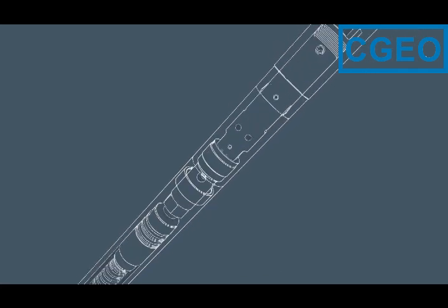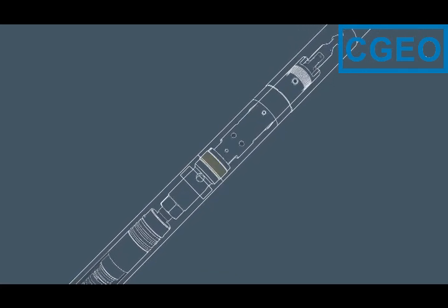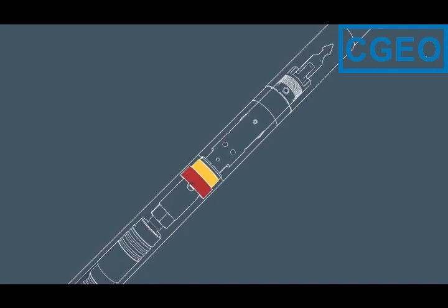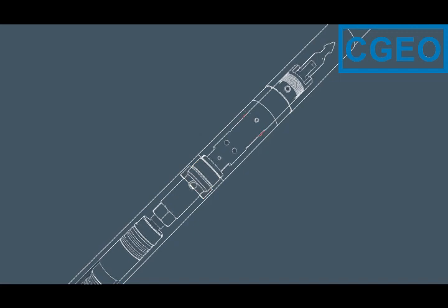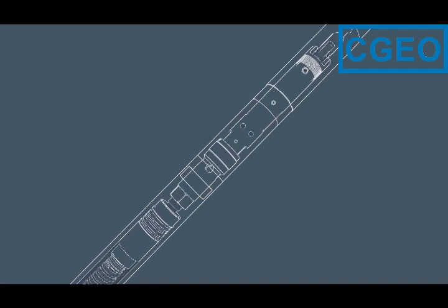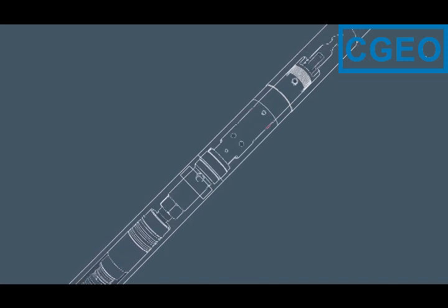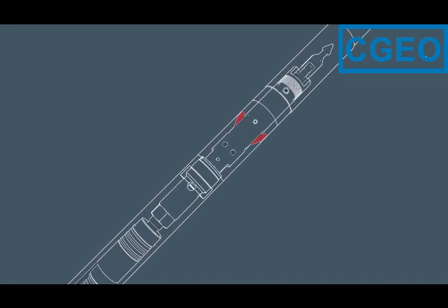The inner tube assembly is fully installed when the landing shoulder lands on the landing ring inside the outer tube and then latches against the lower end of the locking coupling. Without proper latching, the inner tube is loose and will be pushed up the drill string while drilling. To secure a proper latching, most wireline systems are therefore equipped with a landing indicator.